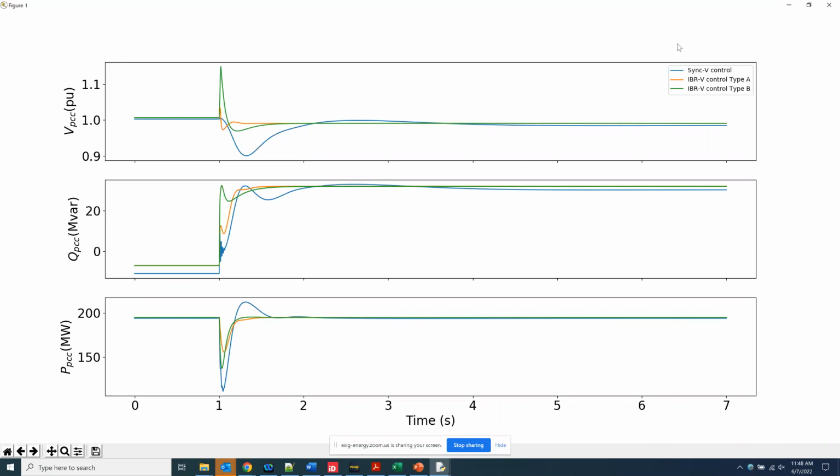Yeah. So going back to a synchronous machine, a synchronous power plant, you tend to consider it inherently grid forming. Without the exciter control, it's a constant source. It doesn't have fast voltage control. And so what you showed earlier was that it is not actually grid forming, because it eventually goes unstable for a large step in grid impedance. Yeah, it may remain grid forming in those first few cycles, and if your intention of grid forming is only to look at those small two cycles, then it's okay.